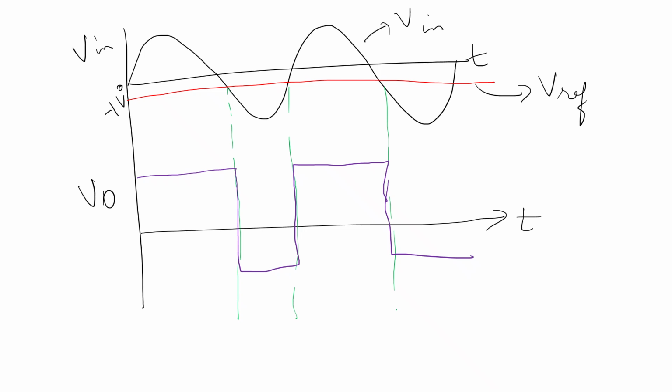So depending on where the input signal is fed in and the reference voltage, whether it is positive or negative, the output waveform swings from plus Vsat to minus Vsat or minus Vsat to plus Vsat until the meeting points of the input and the reference values change again.